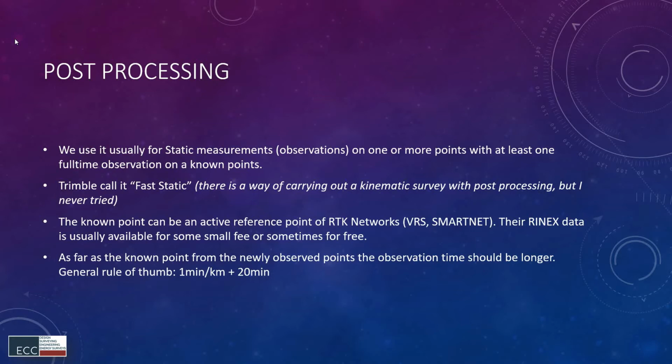So basically, you go in the morning, you start the fast static base survey and start logging. You will see a light flashing on the receiver, and then you can disconnect the Bluetooth and go, and in the Bluetooth settings you will change the serial number for the rover receiver, and you can connect to that and use another fast static.